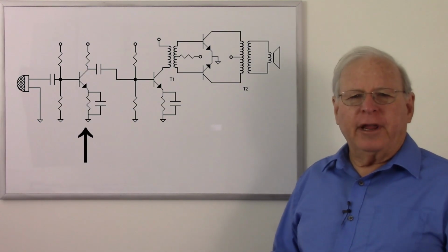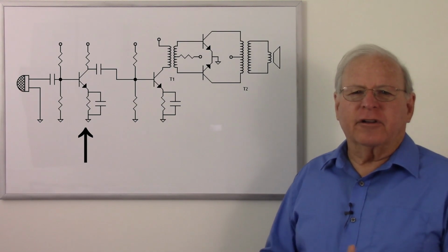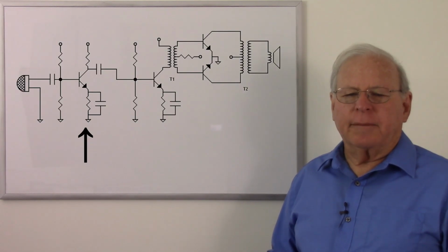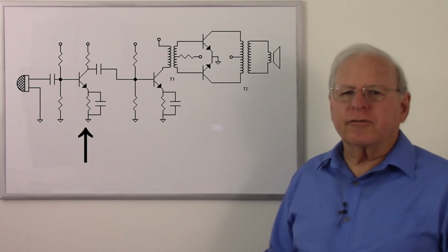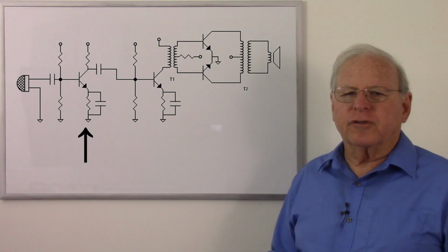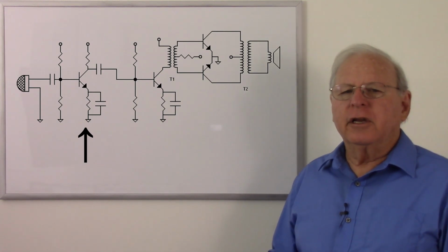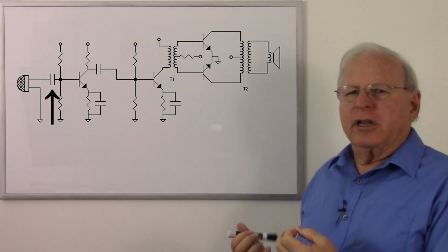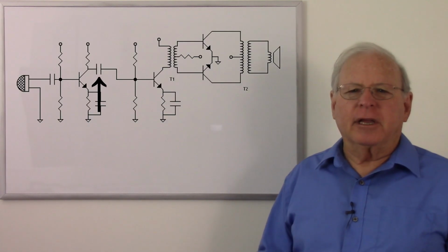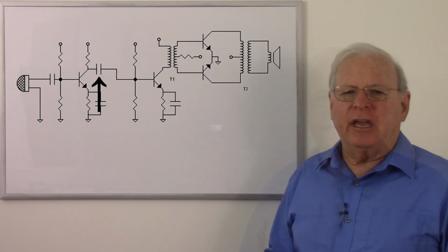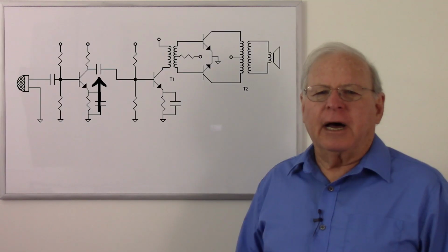So we start out with a preamplifier, which in this circuit is just a simple small signal amplifier, which we've discussed earlier, so I won't go into any detail about the actual circuit, but we just have a single NPN transistor with the supporting components such as the input coupling capacitor and the output coupling capacitor, which couples it to the next stage. And I'll just make a quick mention about impedance matching.